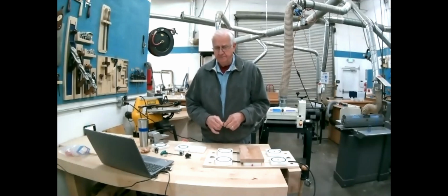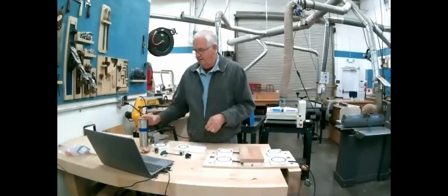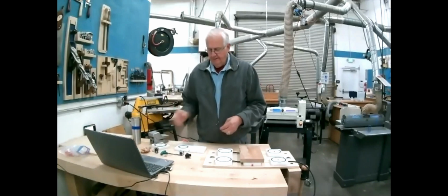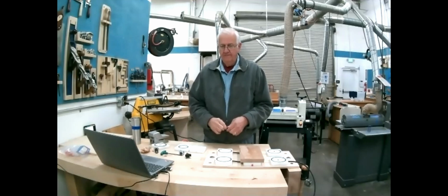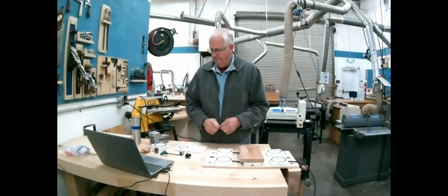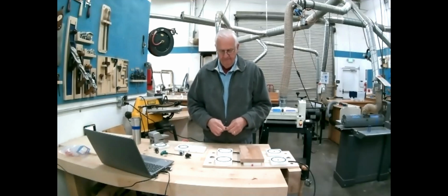Yeah, I'll chime in. This is Doug. I have the 2 CFM from Harbor Freight. It's usually on sale for $80. And like Dallas says, the downfall is you have to make sure you don't put too much oil in the pump. That was my dilemma. I had too much oil in it, and that was a big drawback. But to answer your question, Paul, about the quantity of vacuum needed, you could have a 1 CFM pump, and it's just going to take longer to draw a vacuum than a larger pump. It's all going to get there in the end. It's just how quickly the vacuum will draw with the size pump you have.